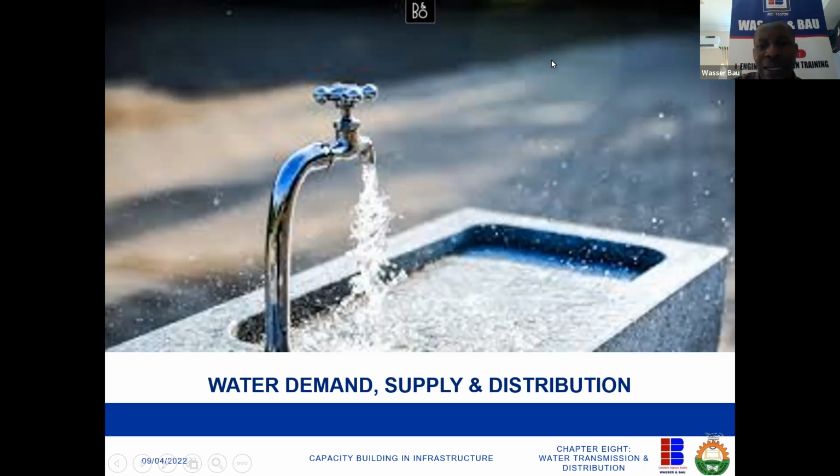After that, you look for a water source. Is it groundwater? Is it surface water? Please put down these steps, even though they're in the PowerPoint. When you get the water source, you ask yourself, what kind of treatment do I need? If it's groundwater, maybe I don't need treatment. If it's surface water, based on the water tests, what kind of treatment is possible? The most conventional, simplest, cheapest, most common treatment is a filtration system.